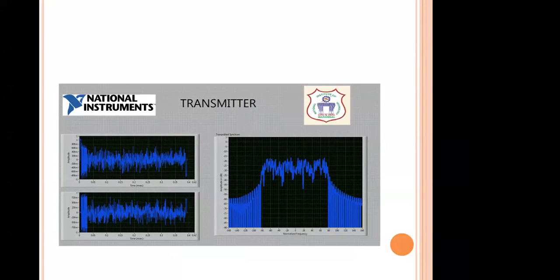From the USRP it goes through the channel in air, and from the air we start decoding the signals. Here the exact timing is also important, so we have implemented new algorithms for timing synchronization as well as carrier synchronization. We targeted both synchronization algorithms, and we could publish good work based on this test bed.